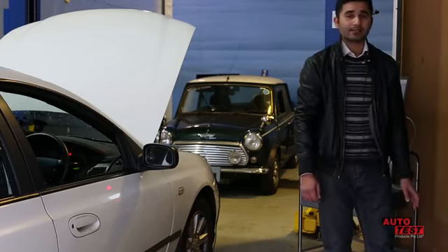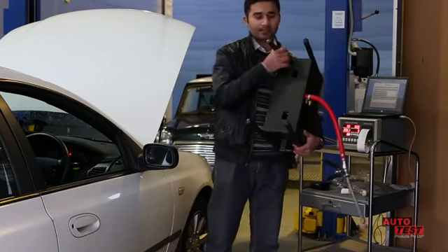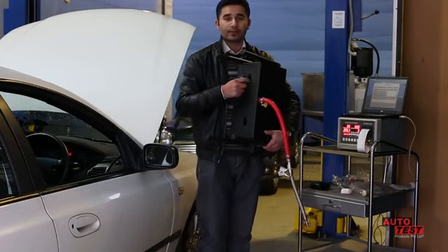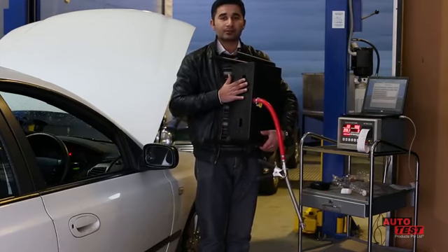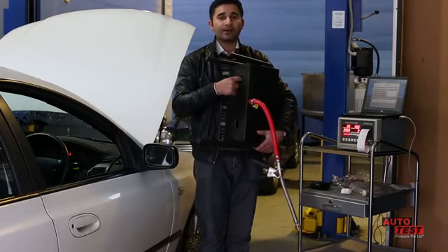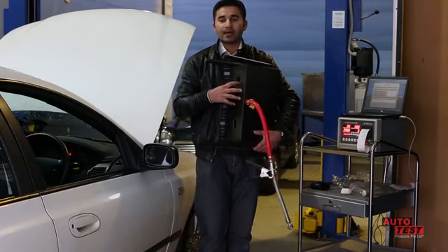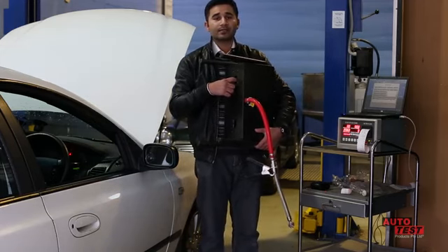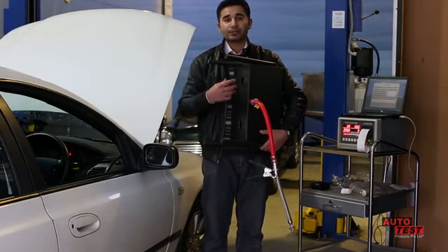I have disconnected the smoke meter, and you can see underneath it, at the bottom, it has two holes. These two holes have lenses or glass at the side wall. When the machine has cooled down, use a cotton cloth and gently wipe the lenses. If you regularly use the machine, a lot of dark black material will stick onto the glass window. If it happens regularly, you should clean it very often.